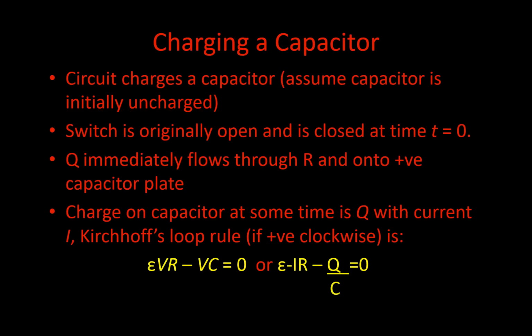You can use Kirchhoff's laws, which we will also discuss or have discussed, and calculate the voltage drops across your capacitor system if you wish. Remember, this is the electromotive force, this is V, the voltage, this is the resistance, and this here is the capacitance. Or the voltage minus Q over C becomes 0.